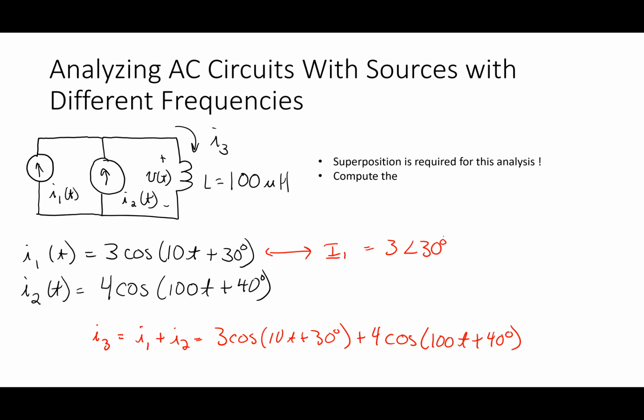So what have I stripped out of that? I said there's three parameters that define a cosine at any given time, right? The three parameters are what? Magnitude, angle, and frequency, right? What have I stripped out? I stripped out the frequency. So the frequency is out of the picture. You are directly implying that all of your analysis is going to be at one individual frequency at that point.